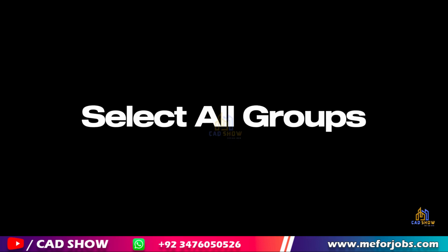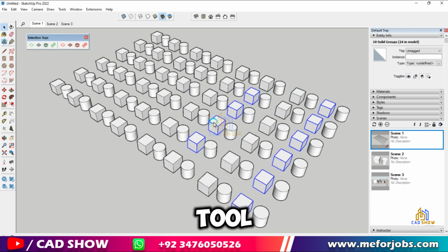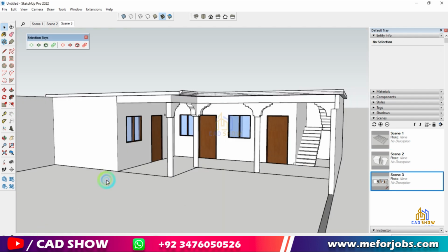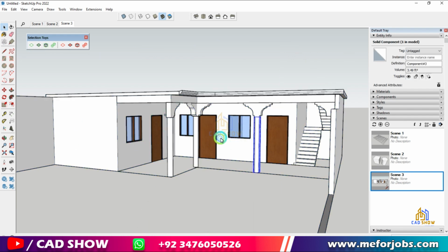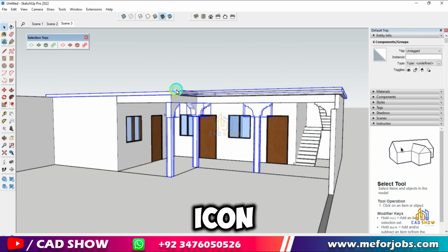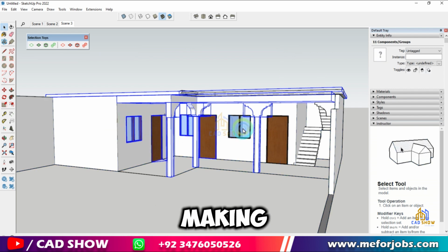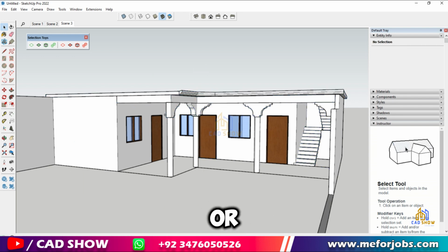Number 3. Select All Groups. The Select All Groups in Current Selection tool is perfect for quickly highlighting all groups within your selection. This tool is a lifesaver when managing complex models with multiple grouped elements. To use this tool, select a portion of your model that contains groups, then click on the Select All Groups icon. All groups within your selection will be highlighted, making it easier to manage grouped entities, whether for editing, moving, or inspecting.